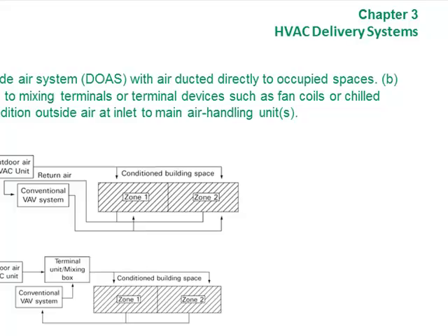No, I don't think you'd have that. Just a constant temperature. Single zone constant air volume is probably what you'd have. And why do you think you'd have that? Simple, it's convenient. Simple and convenient, easy to use. And that's what most houses have. You don't want some computerized system that you need a mainframe to run.